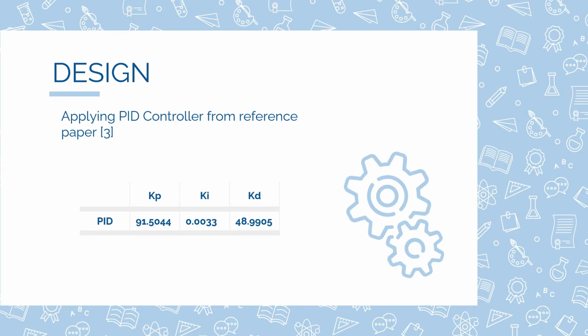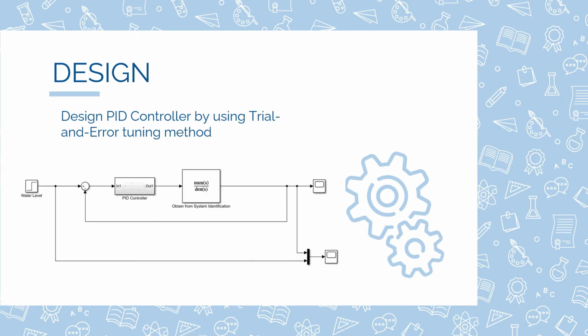The transient response is better than before. Second is the PID controller by using the trial and error method. First, we set integral and derivative terms to 0 and increase the proportional gain until the output oscillates at a constant rate. Once the P response is fast enough, set the integral term so that the oscillation will be gradually reduced. Once P and I parameters have been set to desired value with minimal steady state error, increase the derivative gain until the system reacts quickly to its set point.